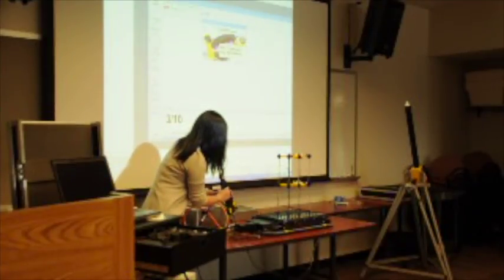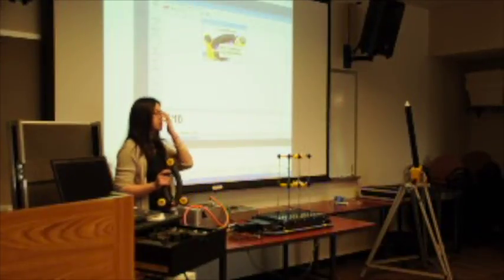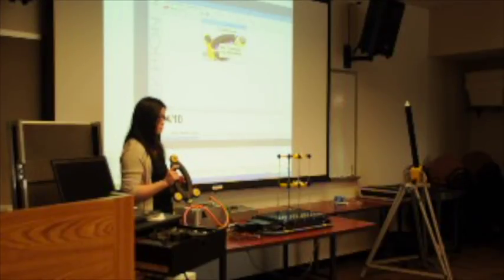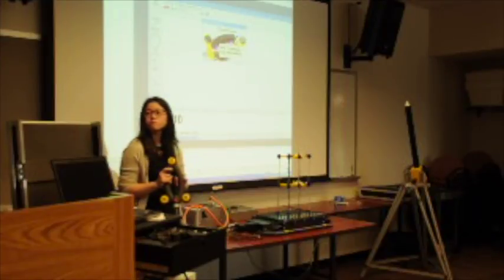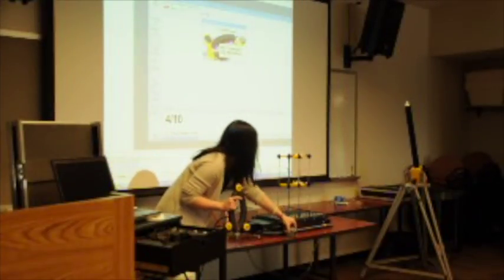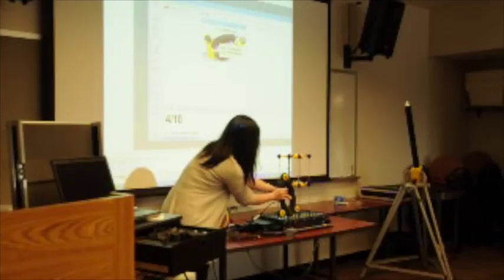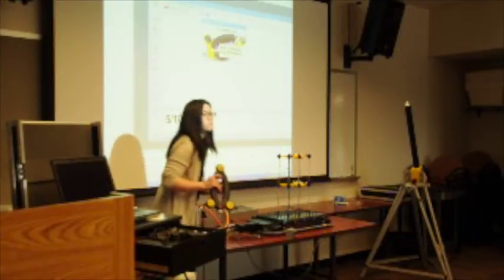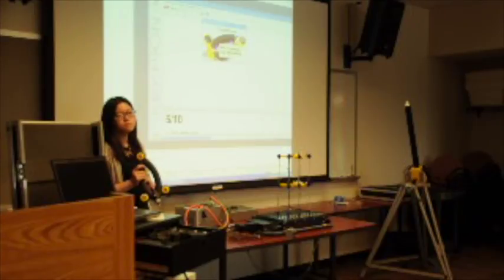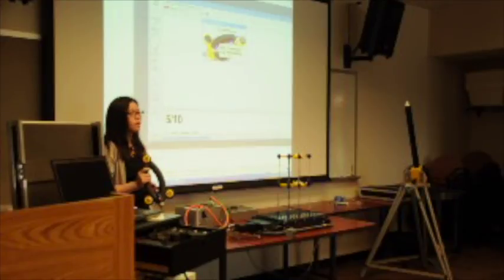In practice, when you have used Krypton to conduct a structural test outside or inside your lab, you have defined planes using information from your specimen or some other reference from your lab? For example, we have done a test on the shake table, so we use the shake table as the plane. If we have a shear building like 3, 4 or 5 stories, we typically use one sensor per floor, and we put those sensors in a vertical line. So you can use that one as the line, or you can use only the bolts on the shake table. That's what we typically do.